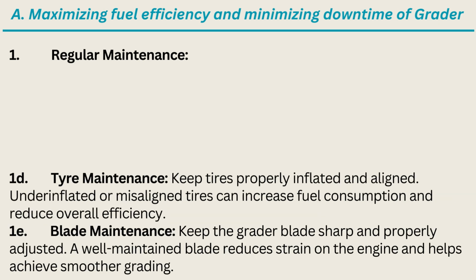1D. Tire maintenance. Keep tires properly inflated and aligned. Underinflated or misaligned tires can increase fuel consumption and reduce overall efficiency. 1E. Blade maintenance. Keep the grader blade sharp and properly adjusted. A well-maintained blade reduces strain on the engine and helps achieve smoother grading.